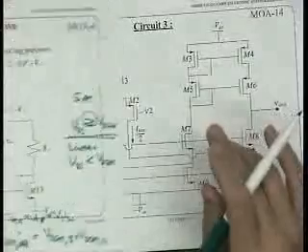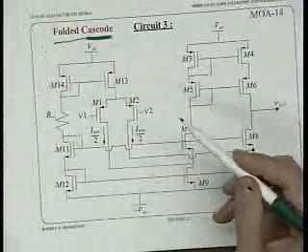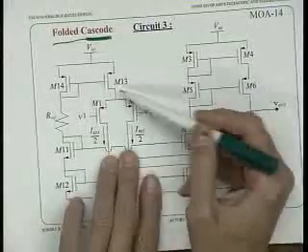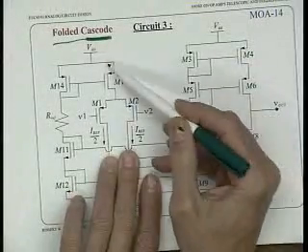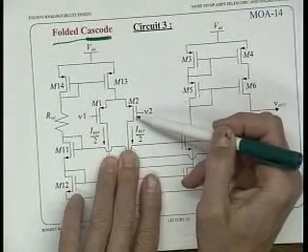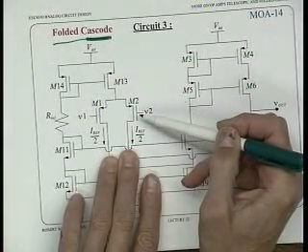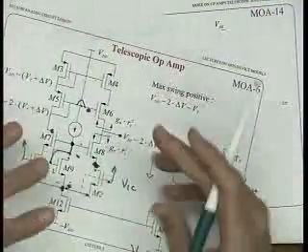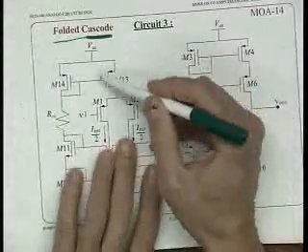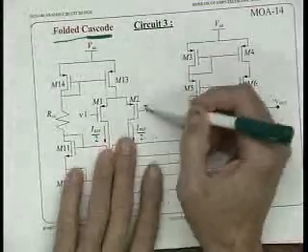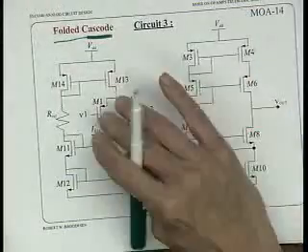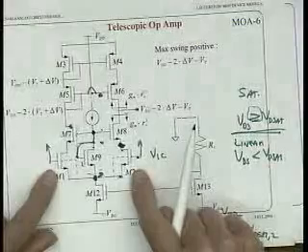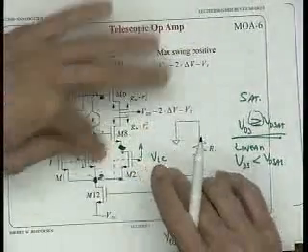So first thing is, probably I shouldn't even have done this, but if we start right there and look at this transistor, here's the input V1 and V2. Here's M13. So this is a PMOS input, okay? So this is being NMOS. So really all I've done is flipped over. So this is the tail current source, M13. Here's the two input transistors. So this is just a flipped over version of M12 and M1, M2. Okay? So just forget all this other stuff.